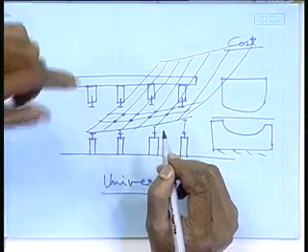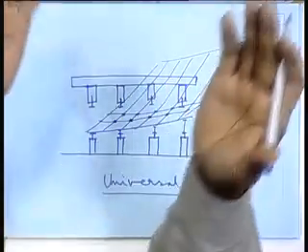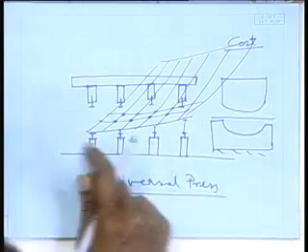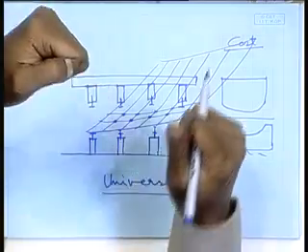So, by means of laser scanning, one can get this data. With that data you generate the surface, match it with the required surface and find out whether it is to be in some place further bent or straightened. Accordingly generate the surface, accordingly actuate the jacks and give the second punch, third punch, fourth punch, and finally it comes out.